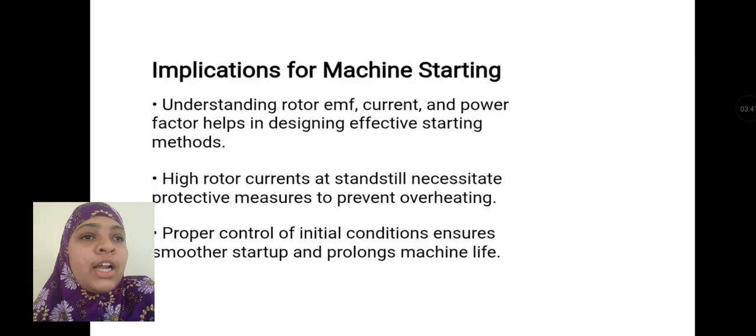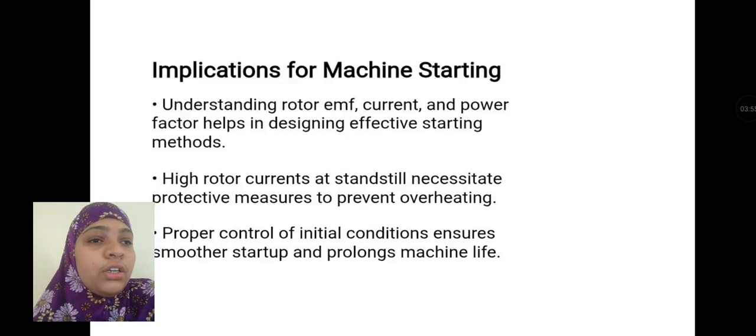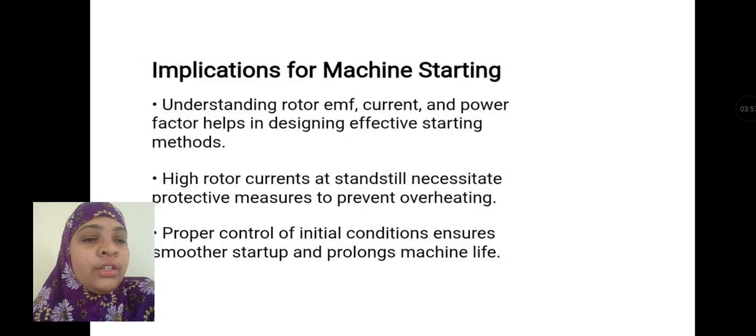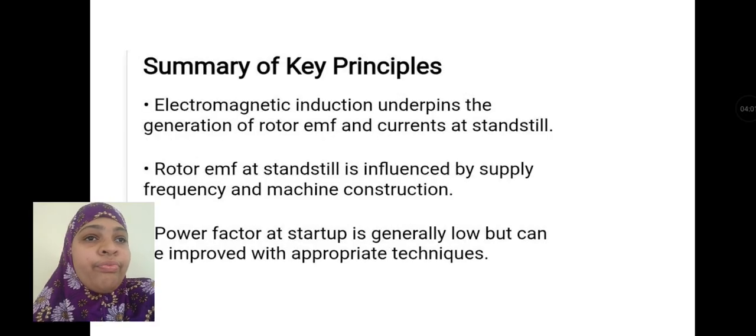Impacts on machine starting. Understanding rotor EMF, current, and power factor helps in designing effective starting methods. High rotor current at standstill necessitates protective measures to prevent overheating. Proper control of initial conditions ensures smooth startup and prolongs machine life.